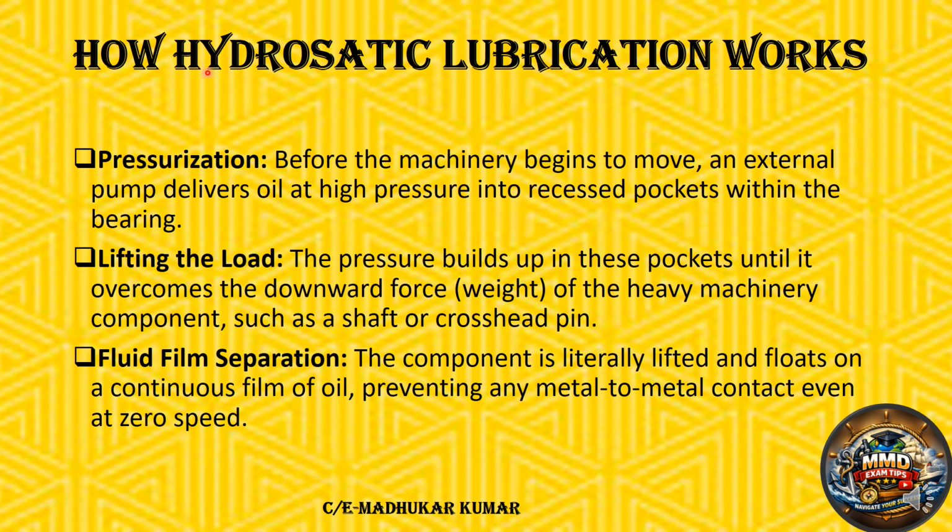How hydrostatic lubrication works: first, the pressurization part comes into the picture. Before the machinery begins to move, while there is no movement, an external pump delivers oil at high pressure into the recess pockets within the bearing. So the pump is pressurizing the oil into the recesses.